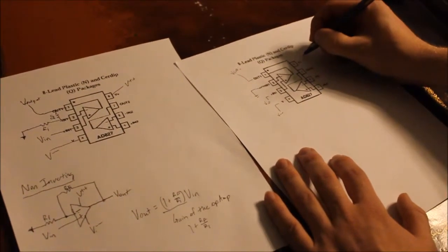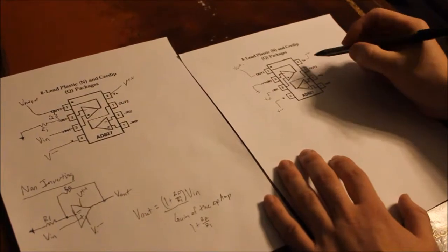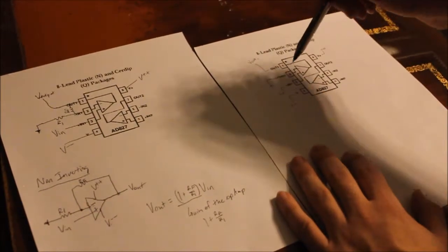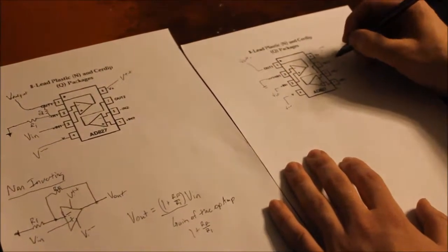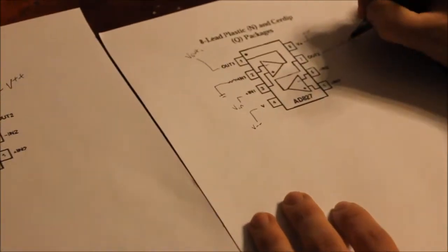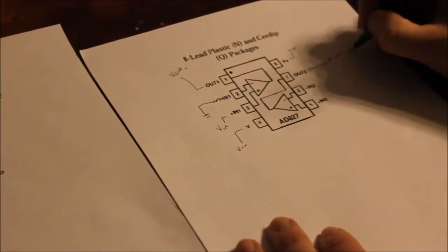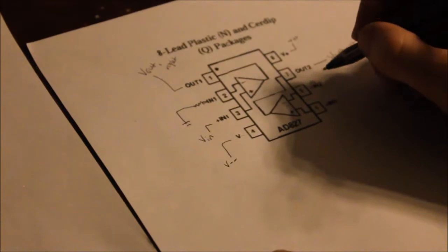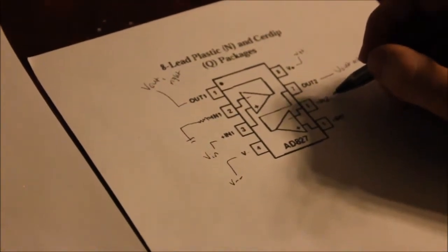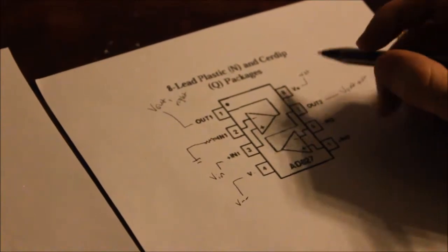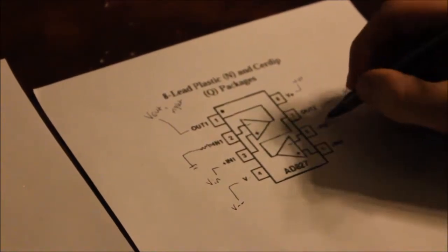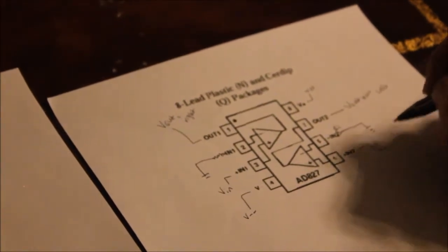You have your positive. And now is where it gets a little bit different, because we're going to start putting in our second input, and it's almost a mirror image to this side. So right here you would have your V out 2, so you can say this is going to be your left side, and this is going to be your right side. And then here, since we're doing a non-inverting, the inverting will go to ground with the resistor Ri, and then this will be the V input from our voltage right there.